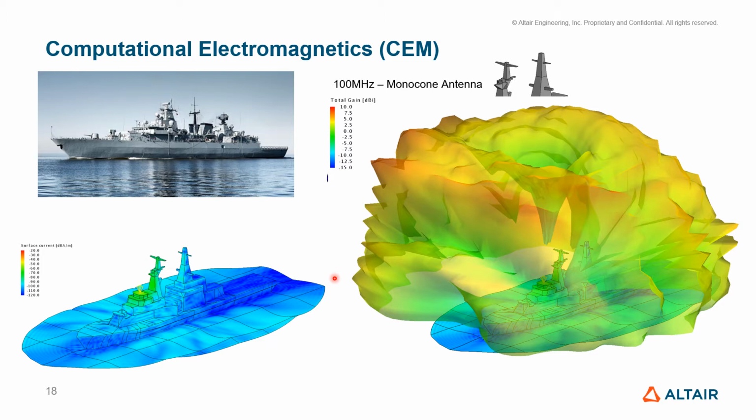So in that respect, when you think of the currents that are flowing on the surface, to represent them, how many points you need per wavelength may be the criteria to be used in terms of how finely or how coarsely you want to discretize your object. As a rule of thumb, based on the frequency, you can say 1/10 of a wavelength is a good number for the size. So what that means is that your discretization depends on the frequency.